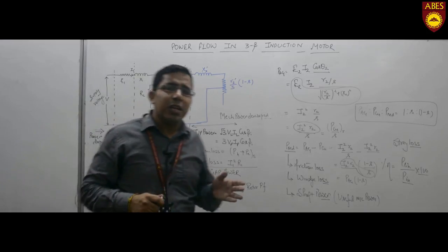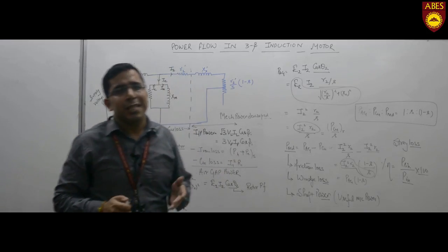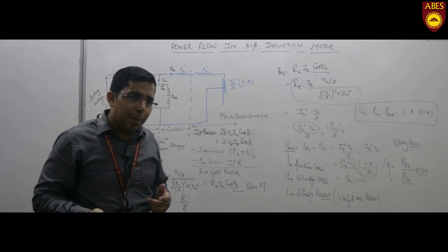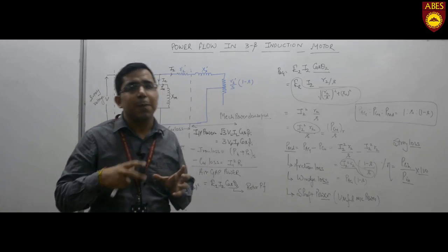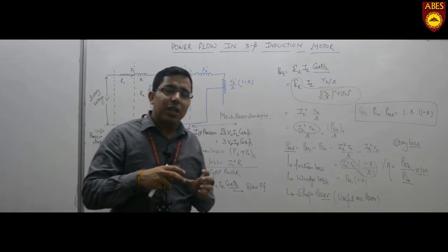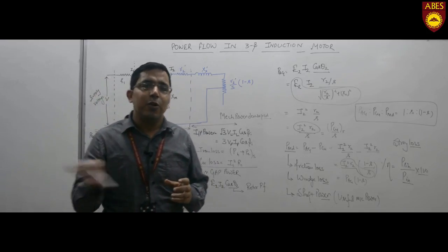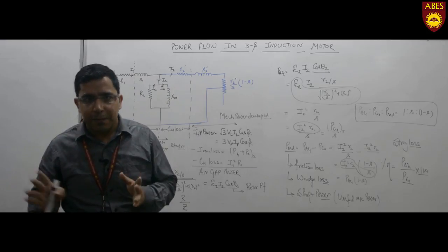However, the wound rotor induction motor has a lower efficiency in comparison to the squirrel cage induction motor because it suffers the losses due to friction at the highest rate. It has slip rings, which increase the friction losses, due to which the efficiency is degraded.